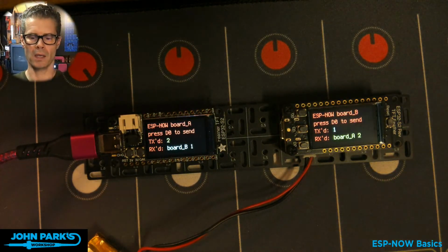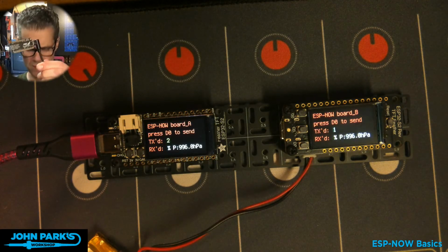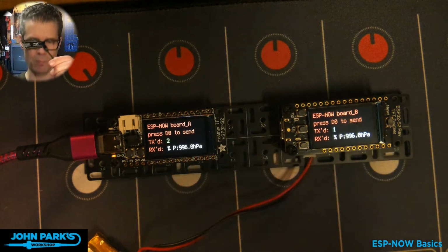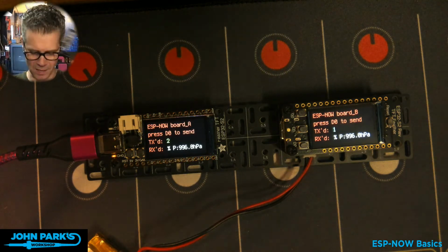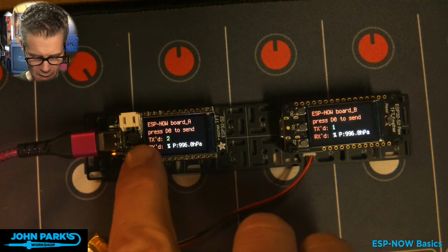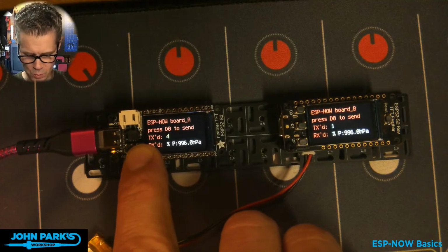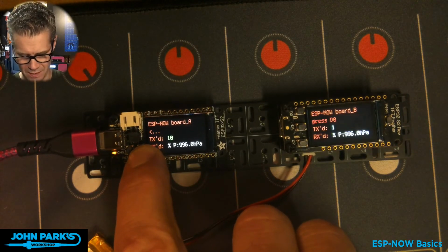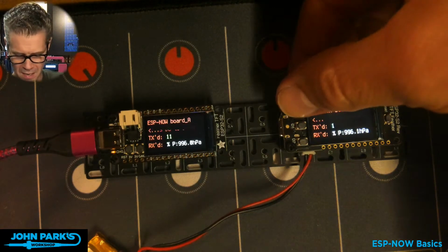So if I broadcast to everybody, this one every 3 seconds or something is going to transmit the temperature, pressure, and humidity off of the BME280 that's on here. So you can see I can still get messages from this board, but then this one's going to send, I think, every second. So I can see all messages are flying in from all over the place.